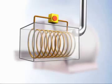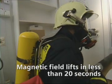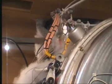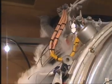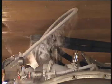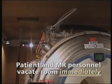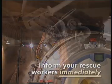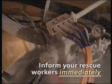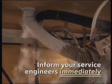This will quench the magnet. This means that superconductivity breaks down and the magnetic field is dissipated within around 20 seconds. Helium escapes noisily through the quench pipe. Due to the low temperature of the helium, skin contact may result in considerable injury. If possible, leave the examination room with the patient prior to pressing the magnet stop switch and inform the service department immediately. A quench is quite expensive because the escaped helium has to be replaced.